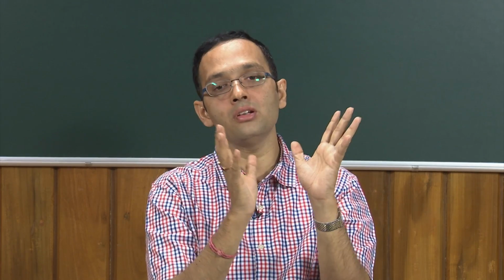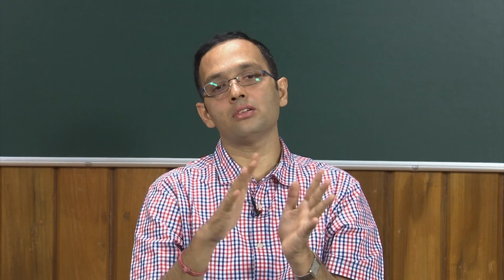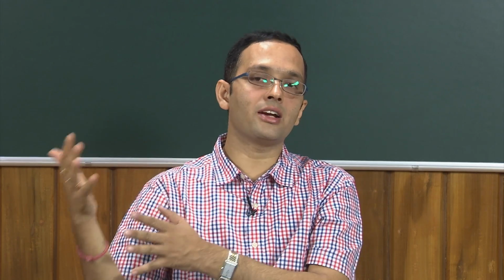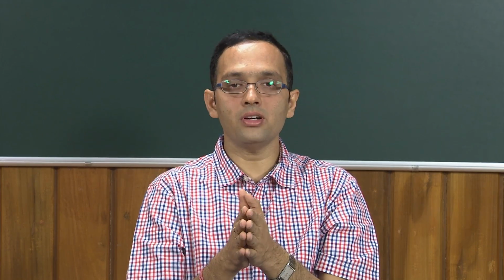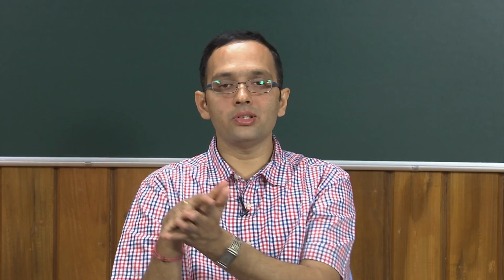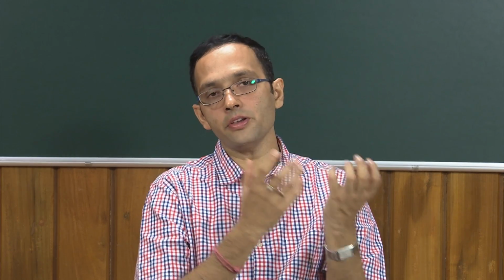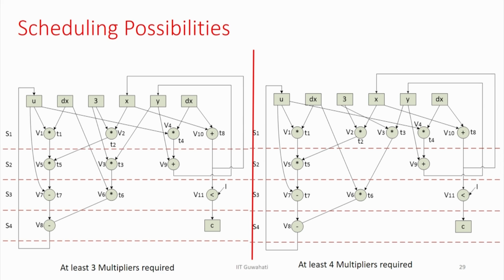So, that is the C code and this is the equivalent RTL, and what we have discussed here is basically how we can generate hardware out of this, the intuitive next step to generate hardware out of it. I have not discussed any automation or algorithm so far. I just showed the logical way to generate hardware, or a register transfer level design, out of a C code or a high level behavior. Now I will not talk about other aspects, I will just briefly give you some idea.